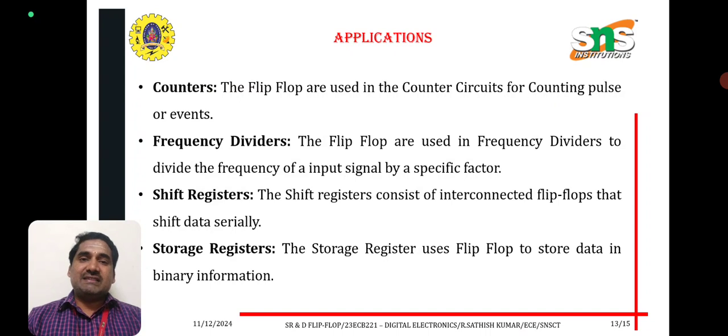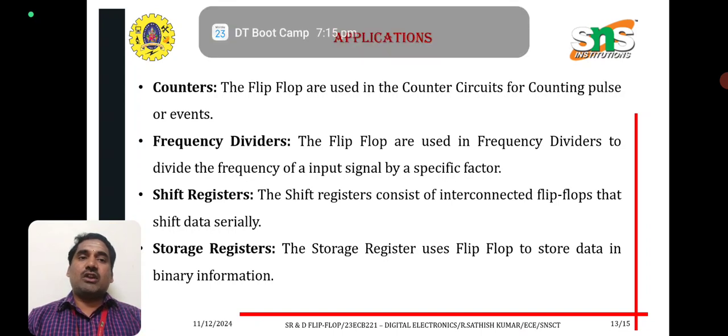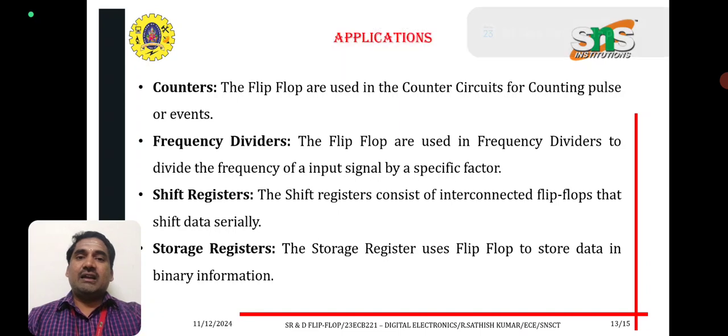Next, applications of flip-flops. They are used in counters, frequency dividers, shift registers and storage registers. Counters: flip-flops are used in counter circuits for counting pulses or events. Frequency dividers: flip-flops are used to divide the frequency of an input signal by a specific factor. Shift registers consist of interconnected flip-flops that shift the data serially. Storage register: the storage register uses flip-flops to store data as binary information.